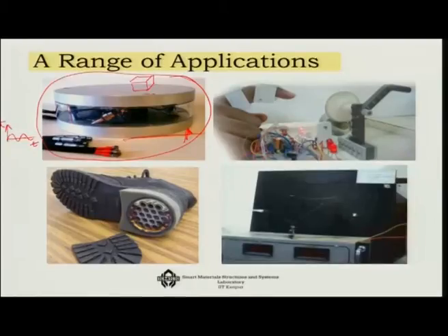So how do I do it? Because this base excitation can keep on varying. One way is to use a piezoelectric material which can change its size. So you can increase or decrease the leg length as and when required, and through that you can stop the excitation from passing through.